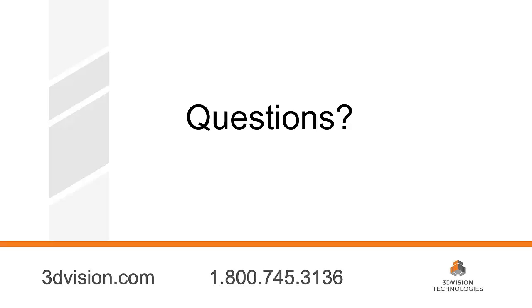Just know that with part files in assemblies, the more faces, the more little tiny slivers of faces they have, the slower your graphics performance is going to be. So that's not an end-all solution to having a big assembly, but it's definitely a factor. It can help.